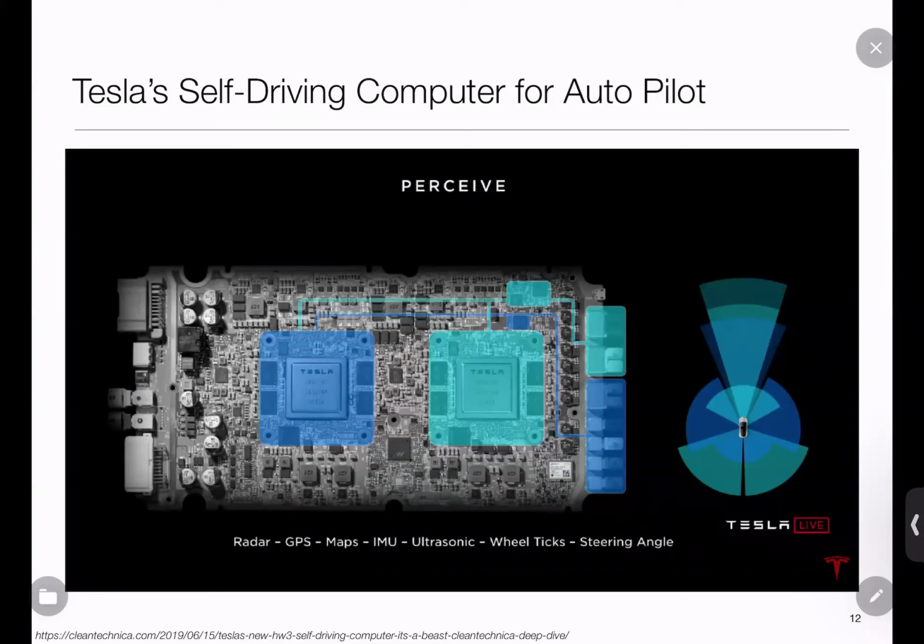Yeah, so LiDAR shoots out laser beams, looks at the bounce, measures the time, gets the depth, and then it scans the laser beam. Actually, it has a curtain of laser beams. Imagine, let's say, 100 laser beams stacked, and the whole curtain is moving and scanning, and it gets a 3D depth map, okay? Then that, coupled with what the camera is seeing, they figure out where the car is. In fact, they pre-map cities with this 3D scan in order to be able to do that. Radar is another thing that these cars use.